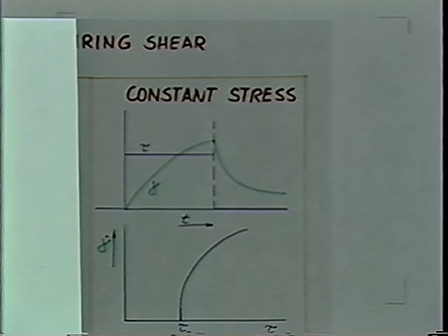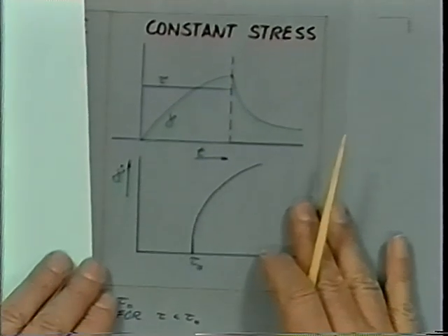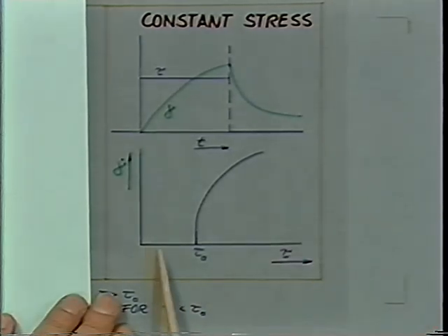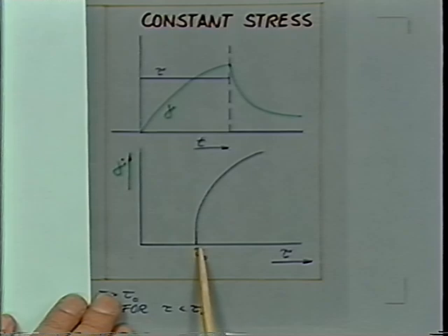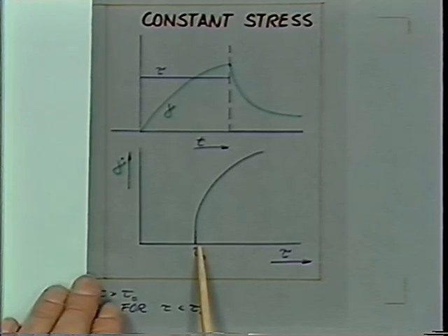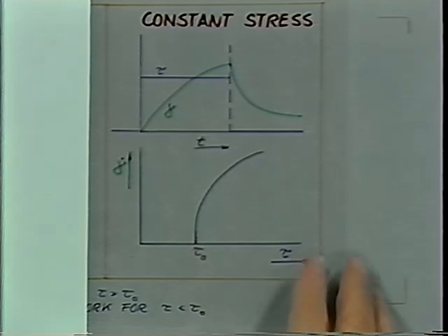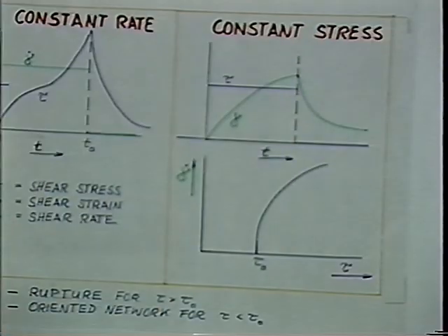Now, if the reaction has been pushed beyond the gel point, then we have to overcome a critical stress level before flow is being induced, and that would be the breaking stress of the soft gel. If you imagine you're spreading Jell-O on your bun, doing breakfast, that's the type of stress you would have to overcome with your knife when you're spreading the material in that, say, food application.